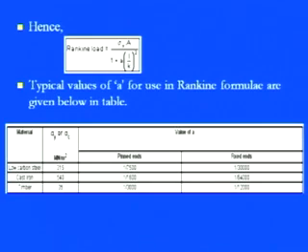But as far as low carbon steel is concerned, based on the microstructure and the kind of load conditions, we always have higher values as compared to the timber part. And cast iron, since it is a brittle and harder material, has somewhat lower values of a as compared to the ductile material, low carbon steel. So this was the correction when n is not exactly matching with those particular values. So the a will come.